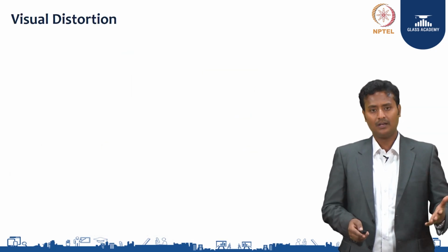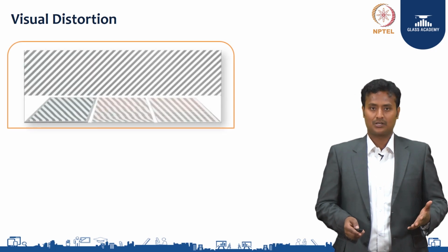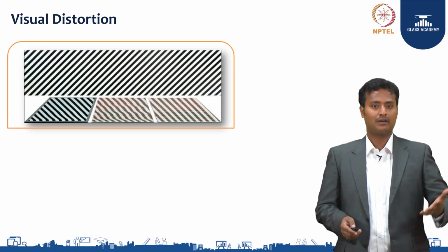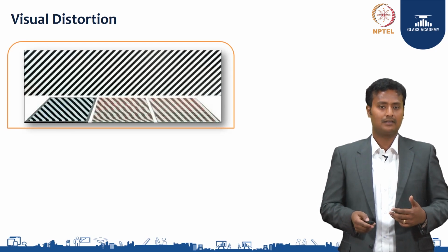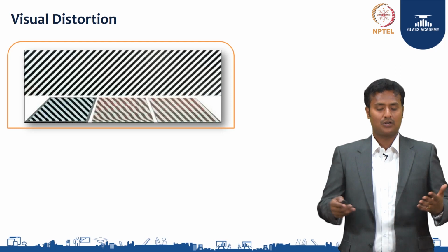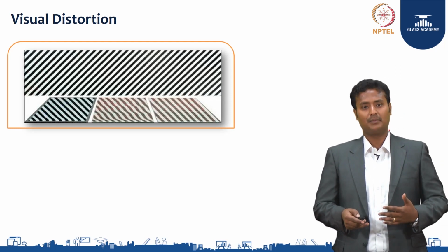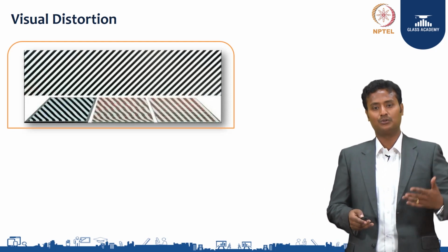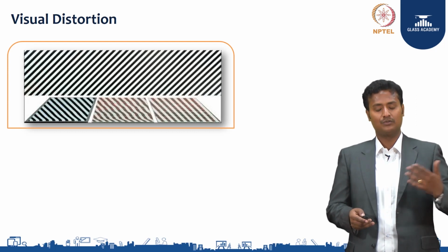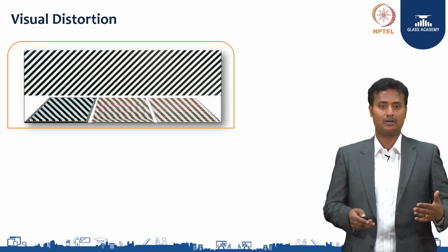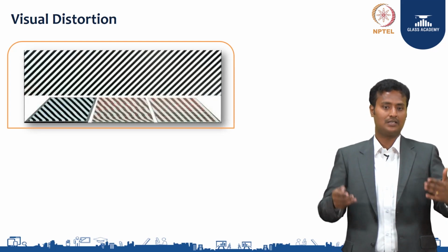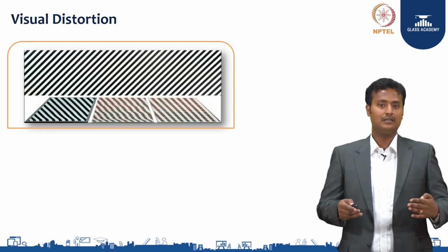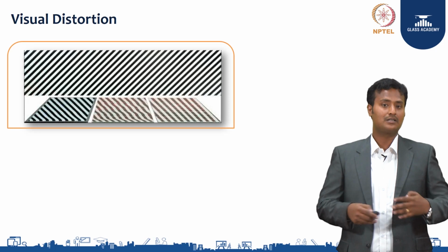In tempering, visual distortion is most important. These are the pictures you would have seen in the tempering line when the glass comes out of the quenching section. You have to go through this process, which is called visual distortion checking. You have to see the zebra line at a 3 meter distance and a 30 degree angle, to see whether the glass is perfectly tempered, or distortion-less, or you cannot eliminate it completely.